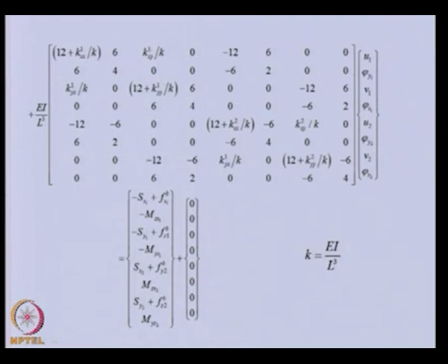So, basically now we get these, and these bearing forces will obviously cancel the shear force, because at the end of the shaft, once we join the bearings, there will not be any net force there. Moment will be there, but net force will not be there. So, they will cancel each other. These terms will get cancelled. The bearing force and the shaft reaction force will cancel each other.